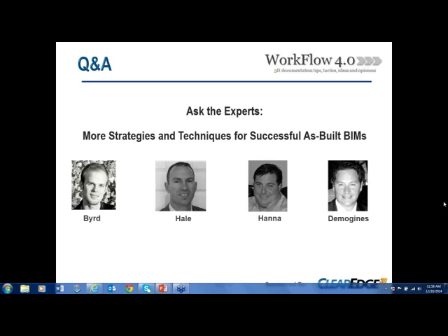So it's really essential that when you're getting up near 1,000, 2,000 scan positions, you really need to utilize survey total stations to constrain your data using survey principles to verify that your targets are accurately controlled, and then the point cloud is being verified against known control through typical survey workflows. So that's what I mean by utilizing survey control.